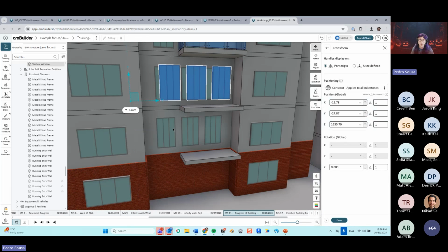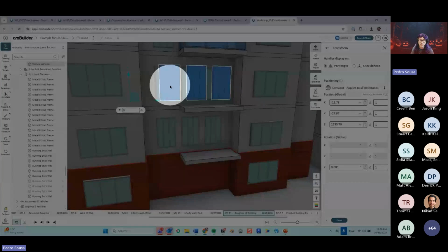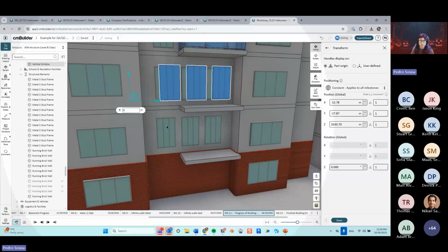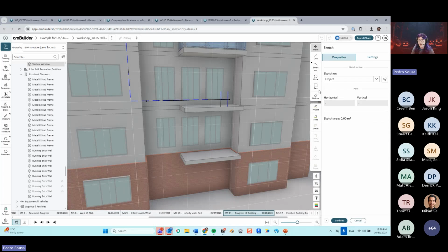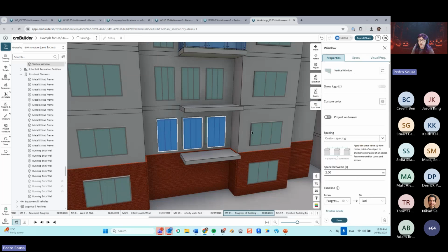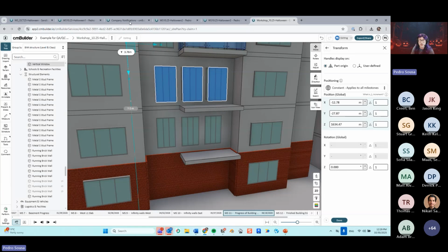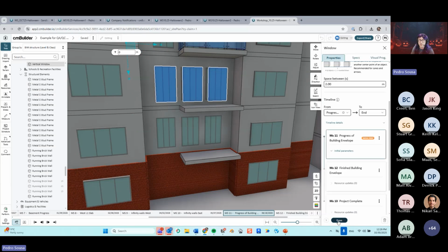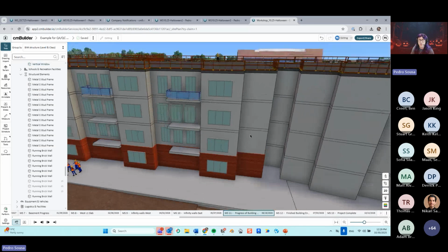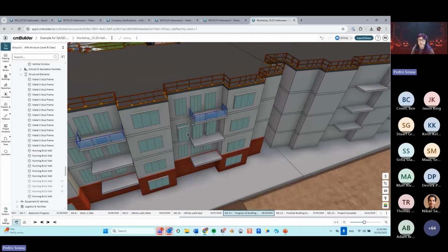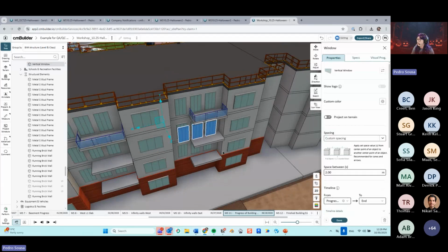And if I want to align these new walls that I copy pasted to the same location as the one below, I can now go into the edit sketch, and then I'm going to redraw and project the sketch from the one below, right? So this will just go and make them at the same location. Then I can go here and then move them up and place whatever I want. Cool. So that way you have several ways of going into that.